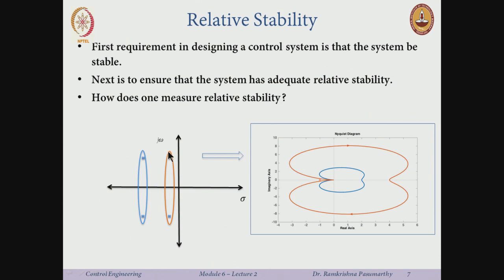Okay, so look at these two things, this brownish kind of color, I do not know what it is called. This is a set of poles here, open loop poles, and these are also a set of poles. Now, this is in my S plane, sigma j omega, these are the poles, also called the dominant poles. I will tell you later why I use the word dominant poles, but let us say the system just has two poles, and I plot the Nyquist for this. So, this blue guy goes here, and this brownish guy goes here.